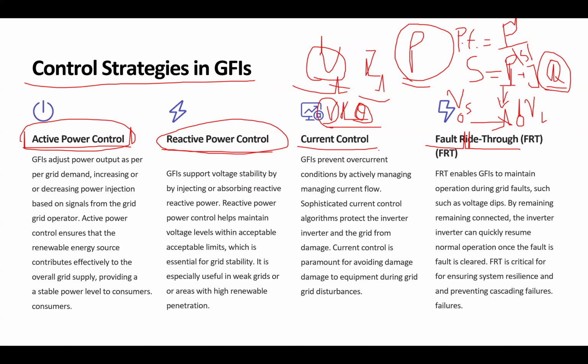Okay, in inverters, in grid-following inverters, we have to follow whatever we see at the terminal. So power factor is not an important indicator in our control system. We don't care if the system asks us for a poor power factor situation, high reactive power, low active power. We are providing them this amount of power.